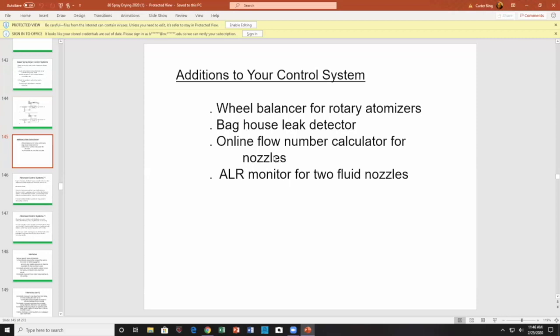The area of the nozzle is fundamental to determining the drop size. Or you may add a gas to liquid ratio monitor, or air to liquid ratio for two fluid nozzles. That should have a minimum of 2, air having twice the mass flow rate as the liquid. Typically with two fluid nozzles, you're looking for the gas stream to cause the atomization. There's very little pressure drop available to cause the liquid atomization. If the gas or the air fails in a two-fluid nozzle, it will likely drip.